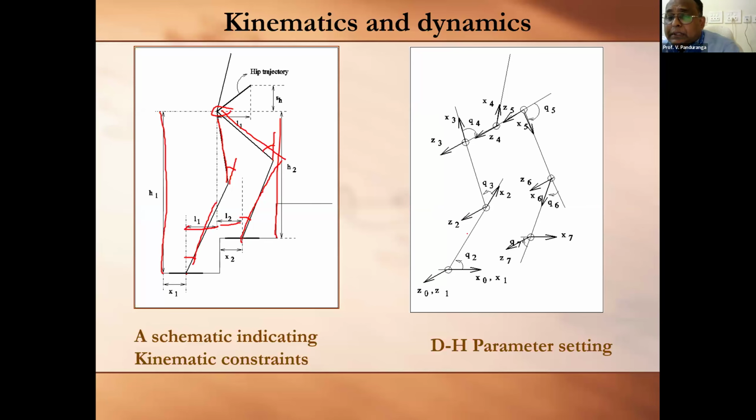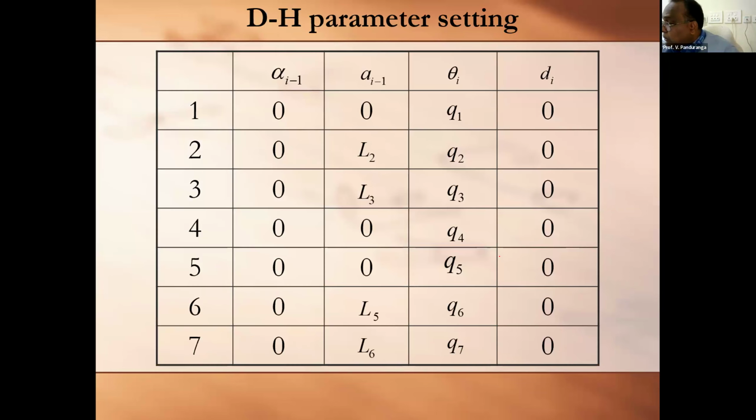Okay, so this is how the DH parameters are assigned at various joints, in order to establish the relationship between the motion of various links. And with that, we have extracted the DH parameters related to this robotic configuration. These are the twist of the link, length of the link, joint angle, and joint offset. These 4 parameters are required in order to derive the forward kinematic matrix.